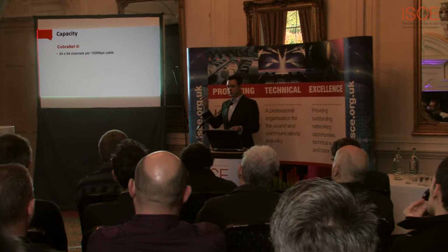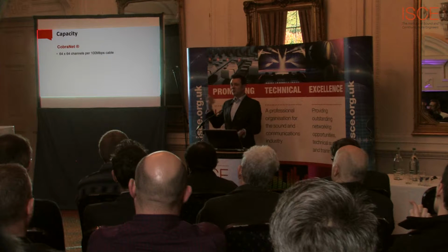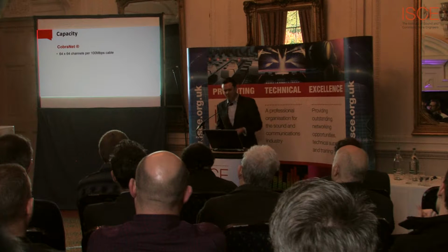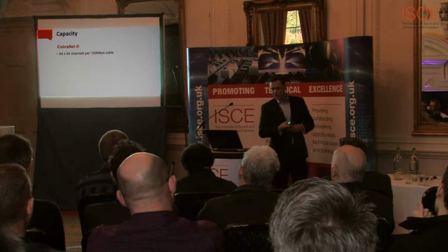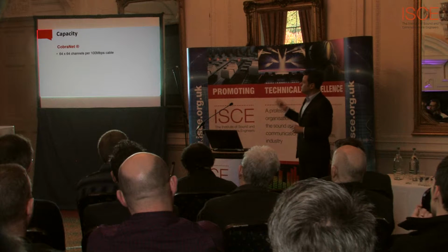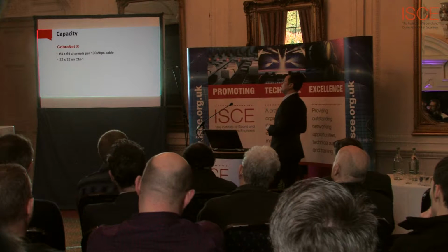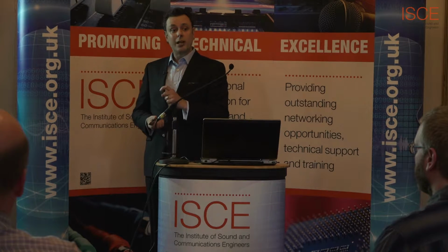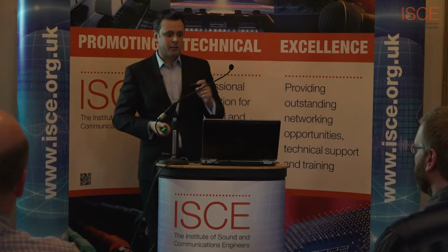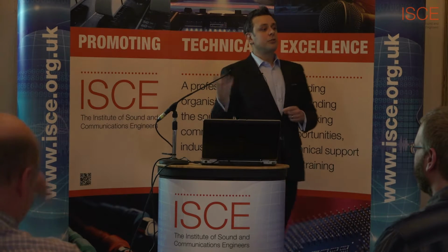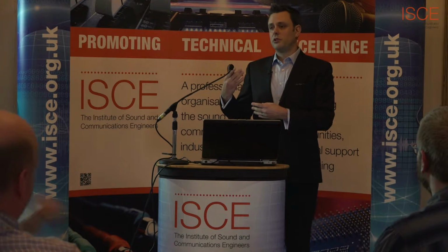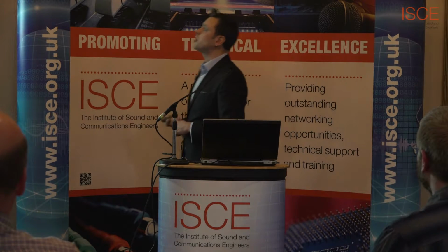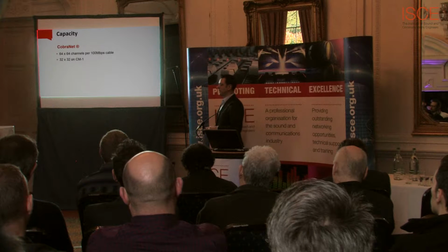Sadly, one of the things that happened when Peak Audio was purchased by Cirrus Logic is that by and large all development ceased. There were some attempts to do gigabit CobraNet, even a proof of concept, but it never really worked. So you can get that, however, on a single module. The largest module they sell, the CM1, CobraNet Module 1, the marketing department spent a lot of time thinking about that one. They allow 32 channels in, 32 channels out. They also sell 16 by 16 and 8 by 8 solutions. So that's pretty much the largest you're going to get in one node.